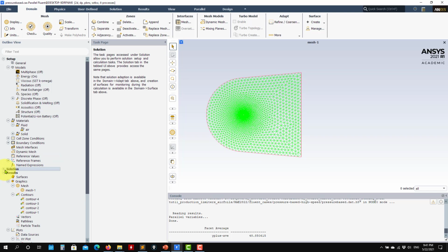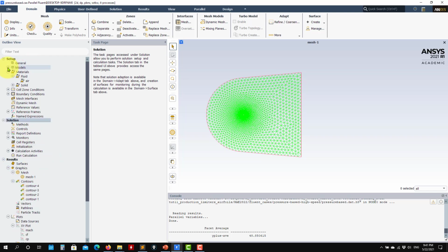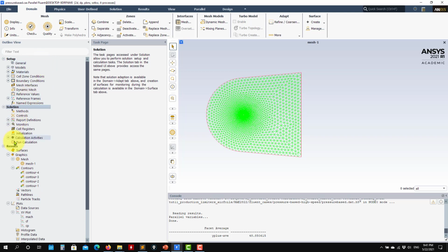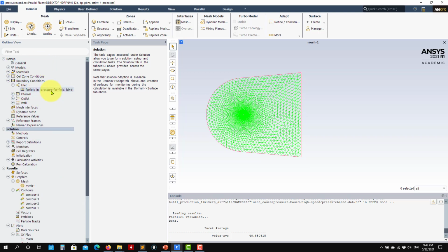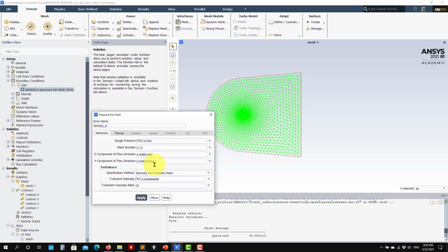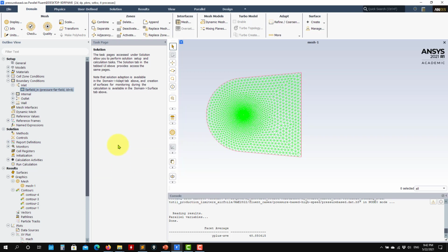And now we go to the case setup, the numerics. So now we address everything here. I invite you to revise everything, and if you want, you can do some modifications. Remember that if you change the incident angle here, you will also need to do the correction when computing the coefficients. This is just to change your reference system to compute forces.